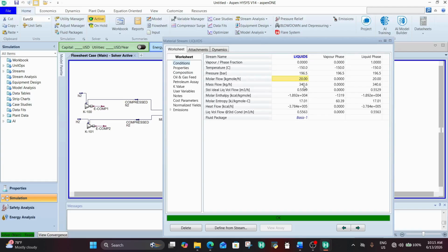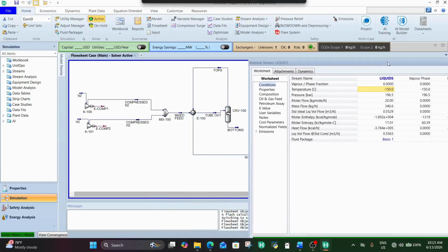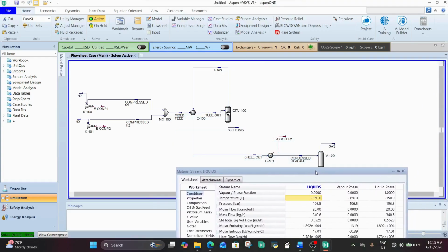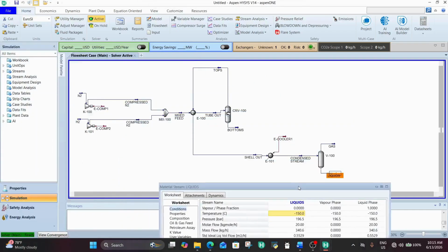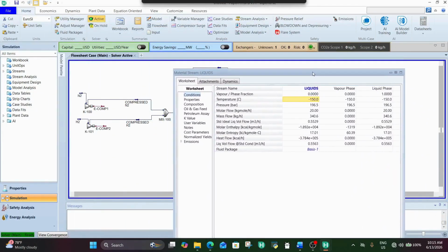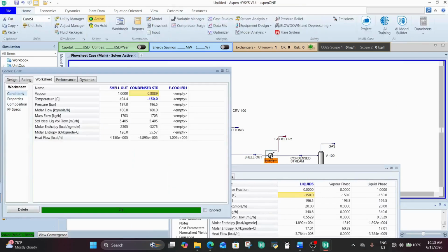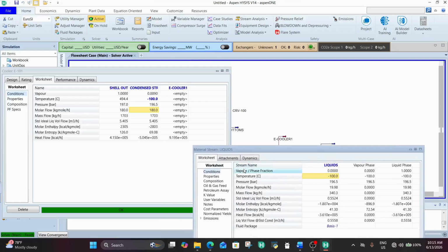Flow rate 20 kilogram mole per hour, approximated from 19.999. So what it's telling us is that at negative 150 with our current pressure, because it's very high, we are able to completely separate, effectively, our unreacted gases from our ammonia. So let's reduce that pressure change. Let's say negative 100, and let's see how it affects us here.